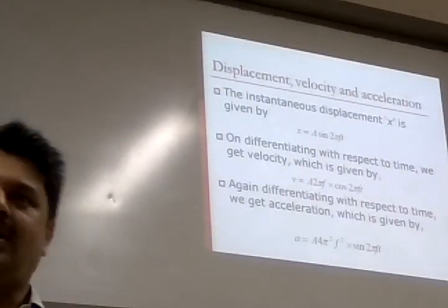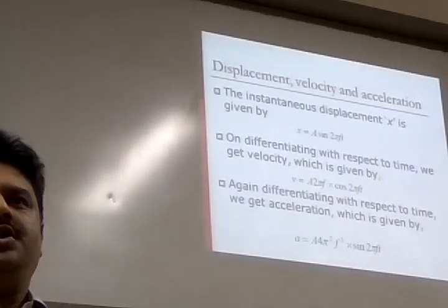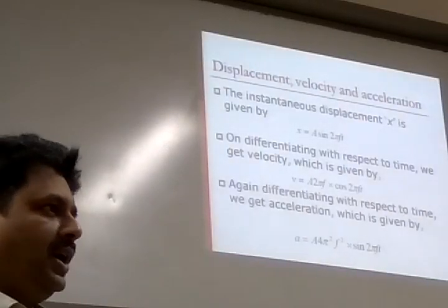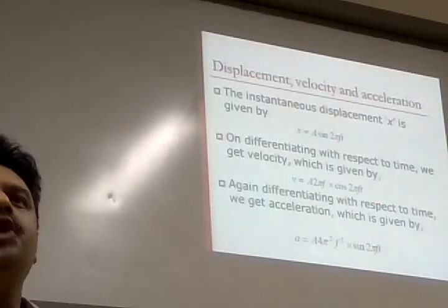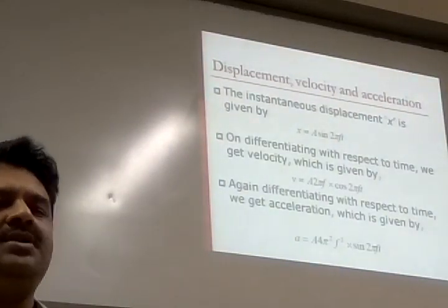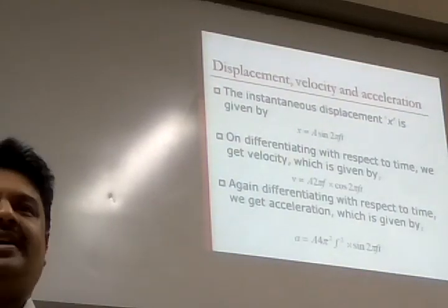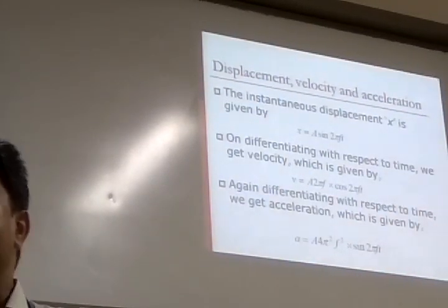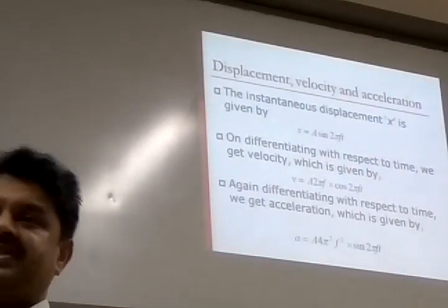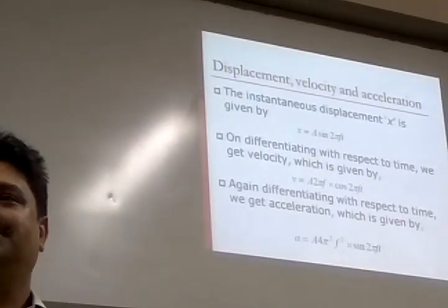to use for measurement. So whenever you go to a company, you have a situation to measure. You want to decide whether you want to measure displacement, velocity, or acceleration. What you should look for is what frequency content I am supposed to measure, or what range of frequency I am supposed to measure. If the range of frequency is very high, close your eyes, measure acceleration.